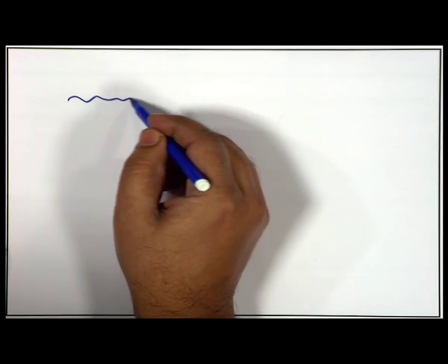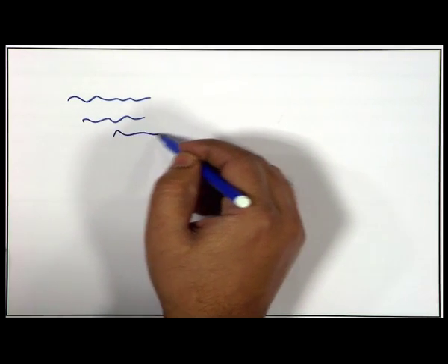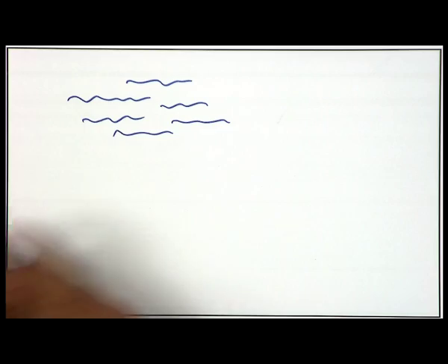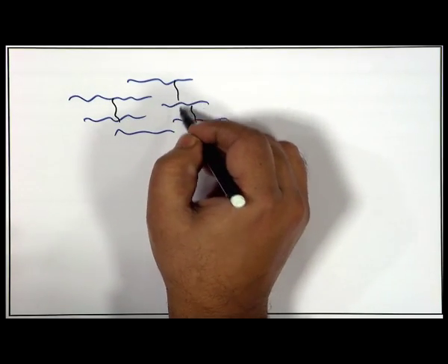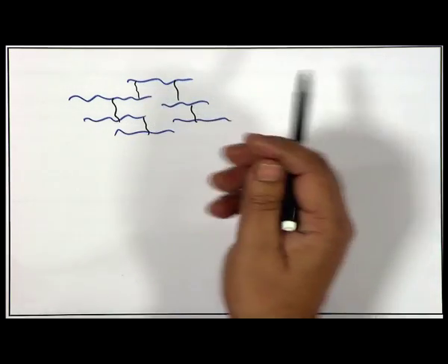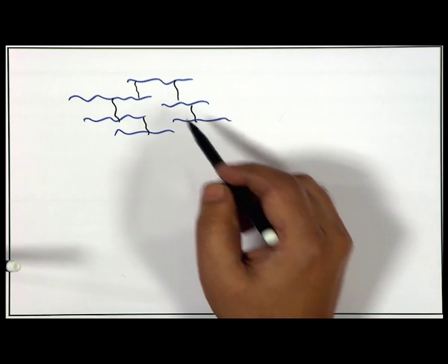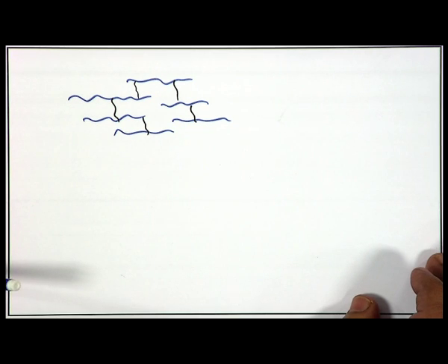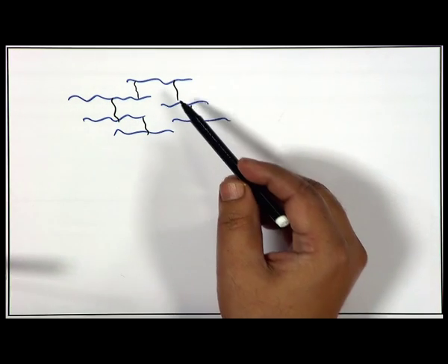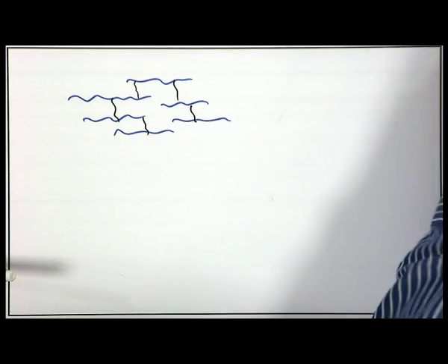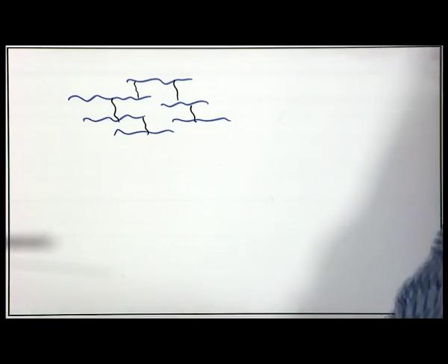So, if I just draw an elastomeric cross linked network type polymer, these are slightly cross linked networks, and if you pull them, because there are very weak intermolecular forces between the polymer chains, they will elongate very easily, but because of the presence of some cross linking, in the later part it will be difficult for you to stretch further.